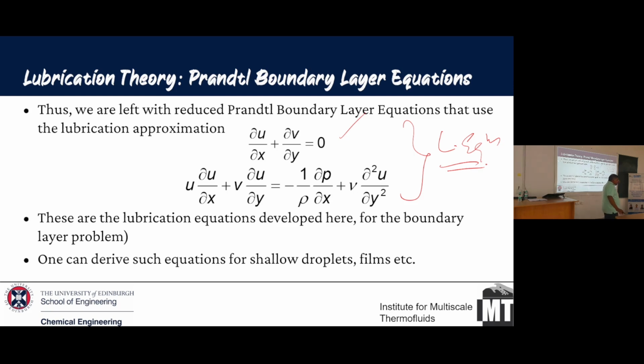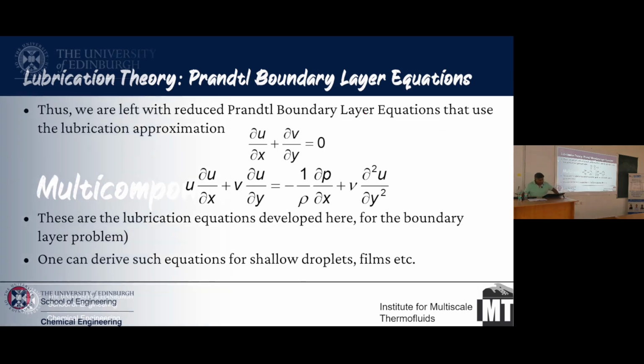Now, what we actually do is when you consider thin films or droplets and you're considering the stability of droplets, rather than starting from the Navier-Stokes equation, you start from lubrication equations. So you can combine lubrication equations with stability analysis because the system is so thin that we can live with it. Okay? So with this, I would like to stop the lecture. Any questions, please?